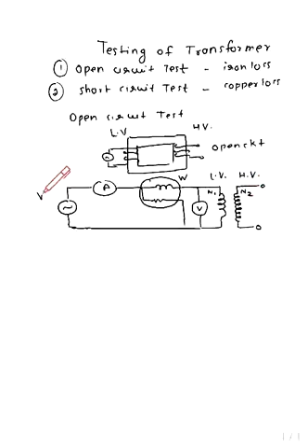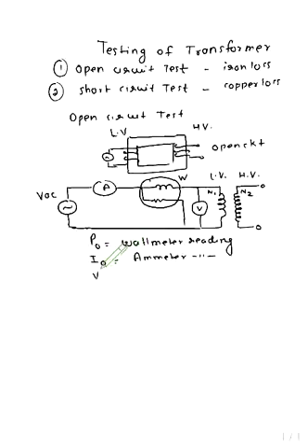So now we will see here, this is the AC supply, VAC. Now we will give the rated voltage supply to the primary winding, so that in the open circuit test we can find the following readings. First we will get P0, that is the wattmeter reading. Then we will find the ammeter reading, I0, and V1, that is called the voltage reading.